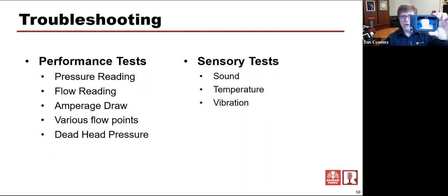And you'll see where the hot spots are, and you'll be able to tell actually what temperature something is at. We've had cases before where we had bearings running very high temperature, or an intermediate bearing on a long pump. Something like this is made by FLIR, F-L-I-R. It's available on Amazon. It's really a cool thing.